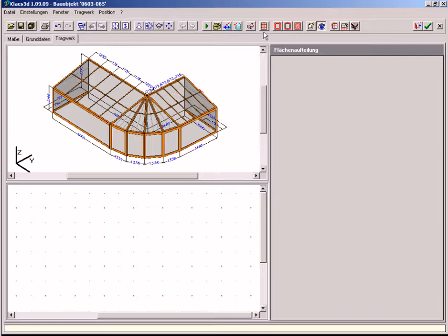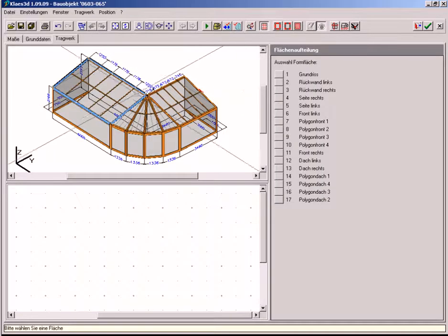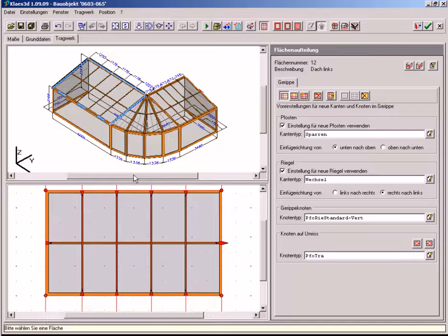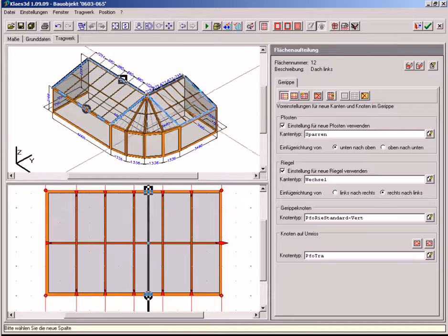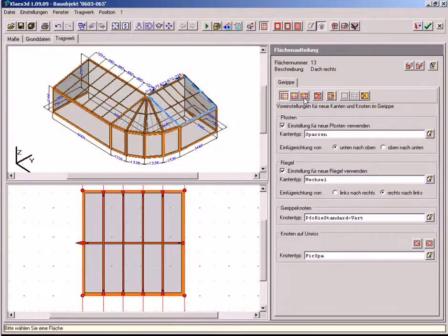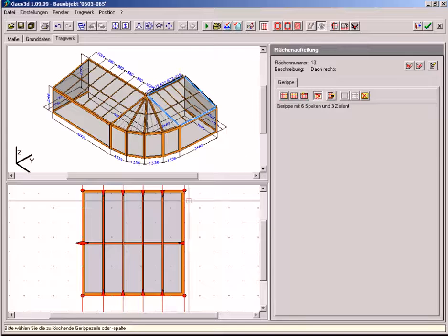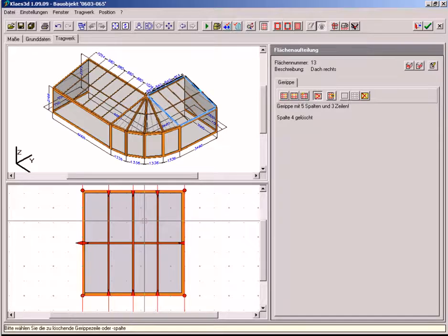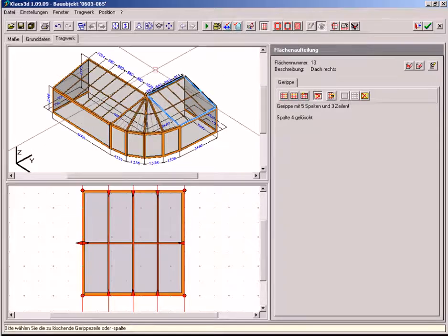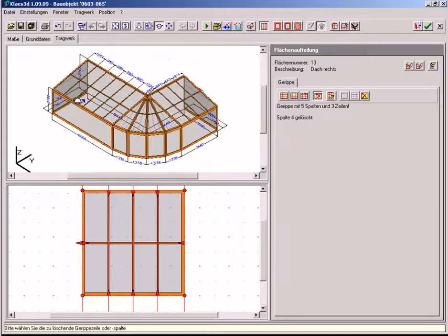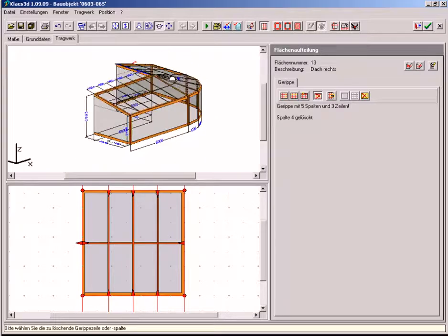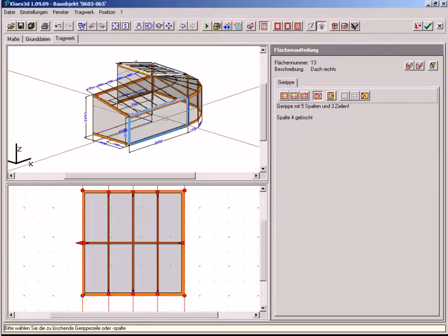Next, the partitioning of the different surfaces takes place. The desired roof and panel constructions can be achieved by adding or deleting rafters and bridging. These roof members can then be lined through onto the other planes by matching up the specific reference points. Dimension settings for the individual partitions can be set and checked within the construction layout.